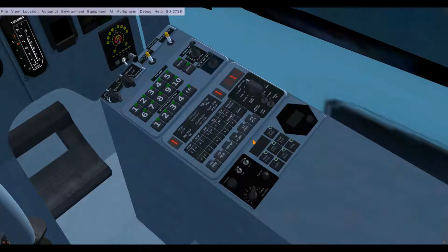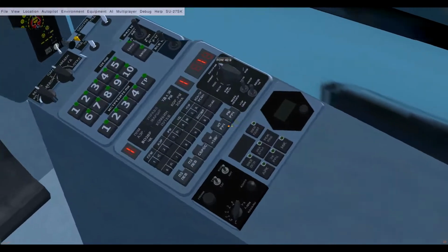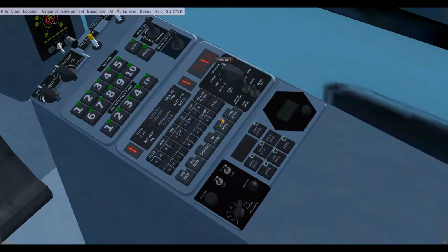The RSBN is very similar to the traditional VOR beacons in range and in frequency band. Some export variants of the Su-27, since it will fly outside the Soviet Union space, have been ported to use the international VOR radio beacons. The ARC as well is simulated here in this FlightGear package as an NDB beacons navigation system, since it's very close to this international system in distance, range and frequency bands.